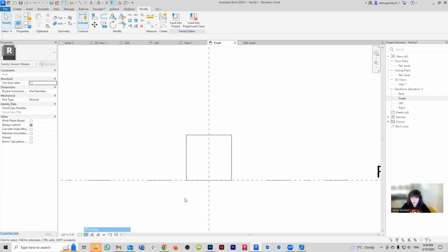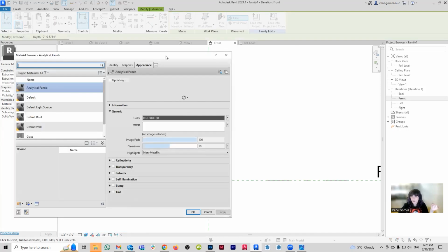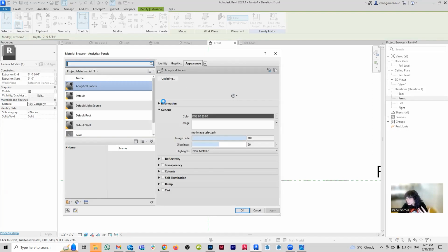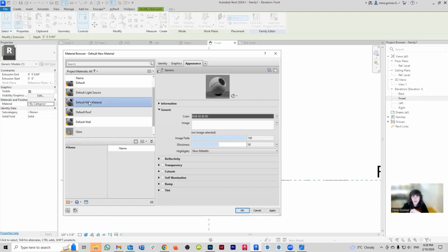to it. So I'm gonna go here, realistic. And what we're gonna do is we're gonna go to materials. I'm not gonna make the material parametric because I don't necessarily want to change the plant, but I will create a custom material for the plant. So I'm gonna go here, new, create new material. And here's my new material. I'm gonna rename it to plant.